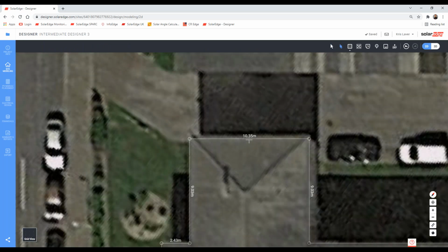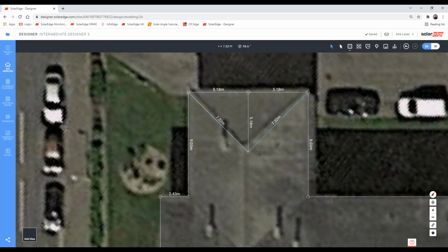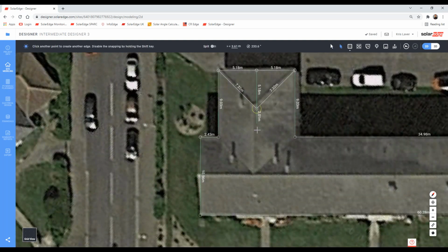So let's find our center point on this hip, which is here, indicated by floating the cursor along this line here, and it will snap and go turquoise in color. I'm going to make sure I've got my 90, and I'm going to wait for it to offer me the suggestion on where to finish the line and connect those up. Now I know I'm perfect here, and the same here. Now I'm going to continue the line and wait for the indication just there. However, I'm in danger of potentially not being directly in the center or overlapping the ridge. So I'm going to leave that there.